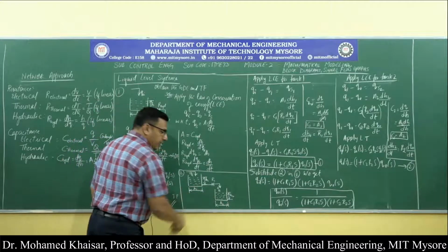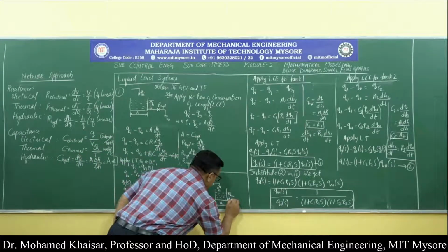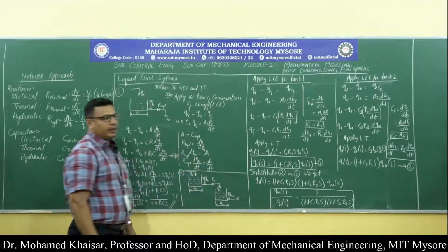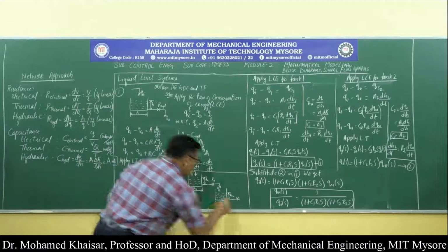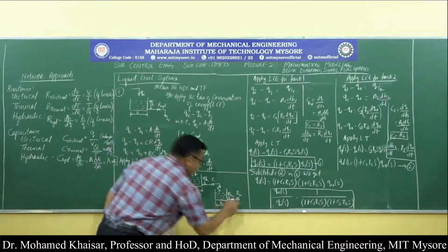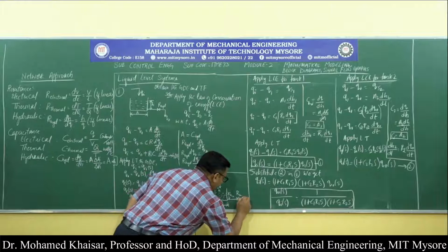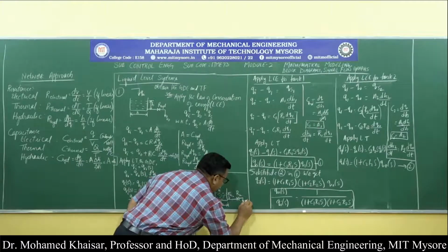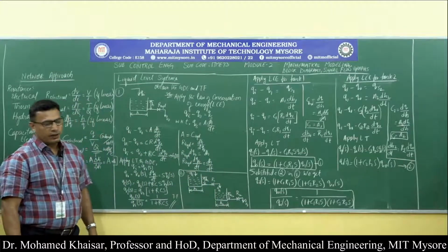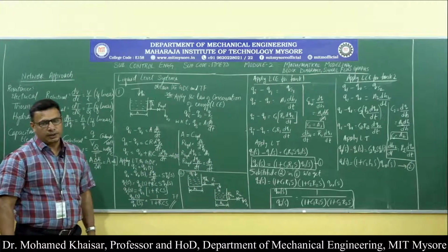This tank in turn releases the liquid outside, again in a controlled fashion, because of the control valve offering the hydraulic resistance R2, because of which the liquid flows out at the rate of Q0.